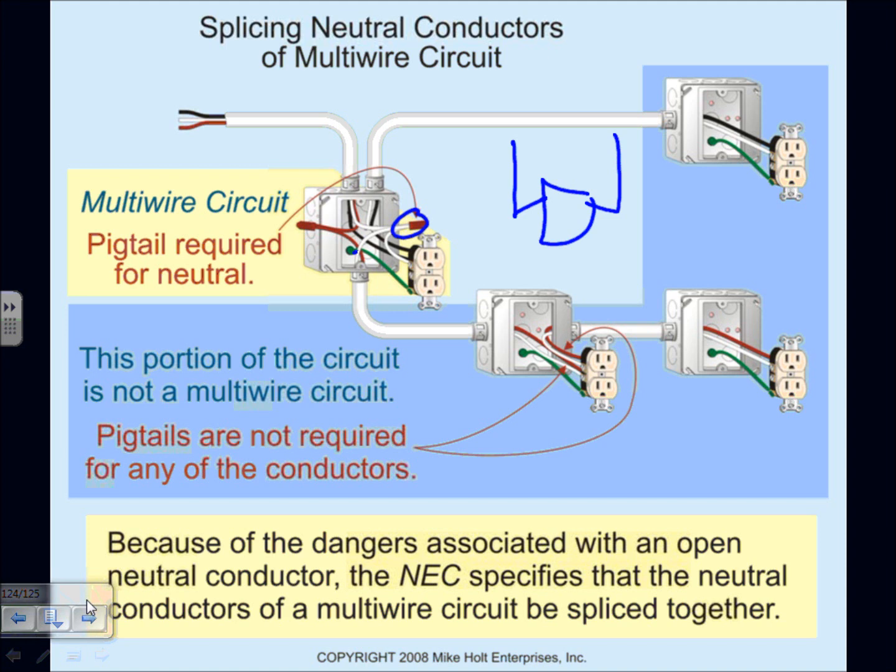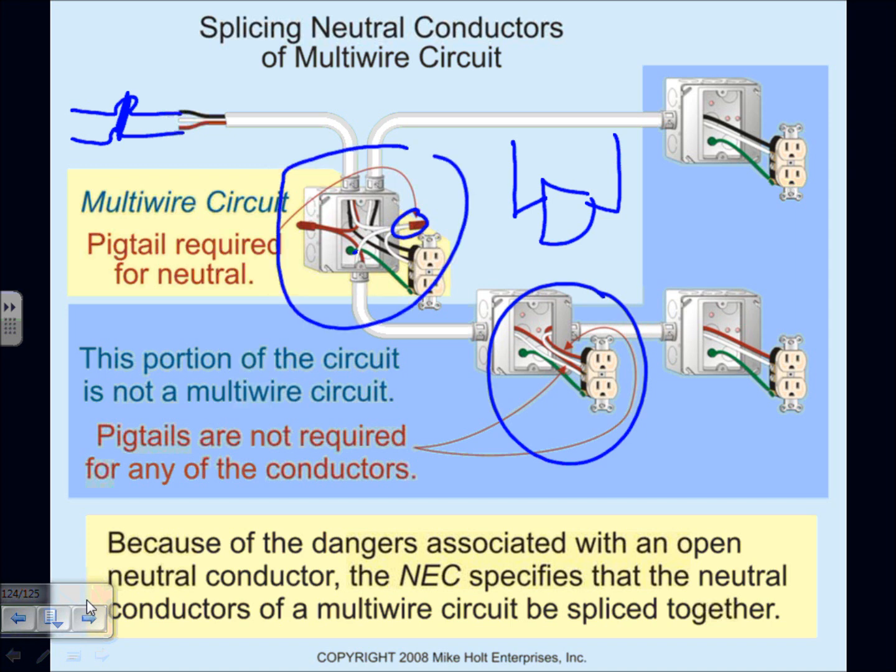You don't short. If you short circuit, that's beautiful. The circuit breaker trips, but here you burn equipment without any warning. Because of this, guys, the code changed in 2000-and-some, I think 2005, and they said if you have a multi-wire branch circuit, we want you to tie both breakers together at the same time. The reason is that if you're doing maintenance on this side, you're supposed to turn the circuit breaker off. You can turn both of them off, and you are guaranteed that all the power is killed in every aspect of this circuit. Any question, guys, about this?